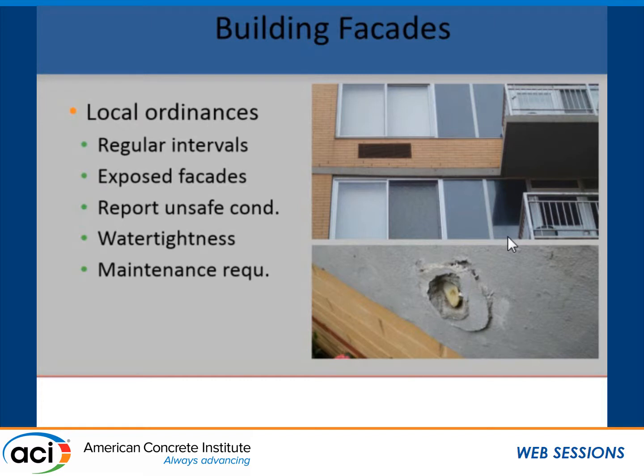These are the types of things that you may see, but the more interesting one, and this is new construction, this is a condition where there was a post-tensioning grout pocket that was popping. There's two questions I have there. First, is that grout pocket that's popping a potential hazard? And second, why is a post-tensioning grout pocket falling on a brand new building? So these are some of the types of things that you'll see and maybe have to understand the implications of when you're doing a facade inspection.